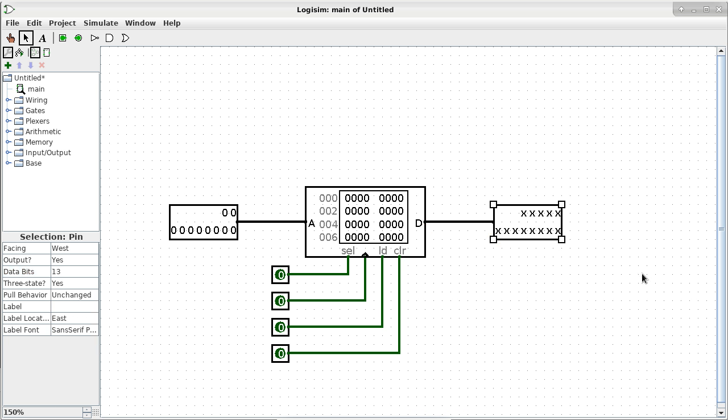Okay. So now we have all the basic ports to access a particular RAM component, and we can start to experiment with it. You can see how the A port has a different width compared to the D port. Once again, the A port is controlling how many locations we have in this RAM. Since we have 10 bits, it's 2 to the power of 10, which is 1,024 locations. On the other hand, the width of the D port, which in this case is 13 bits, is controlling the width of each location. So each location of this particular RAM component has some really oddball number of bits, which is 13, okay? But, hey, if this is what we want, this is what we can get.